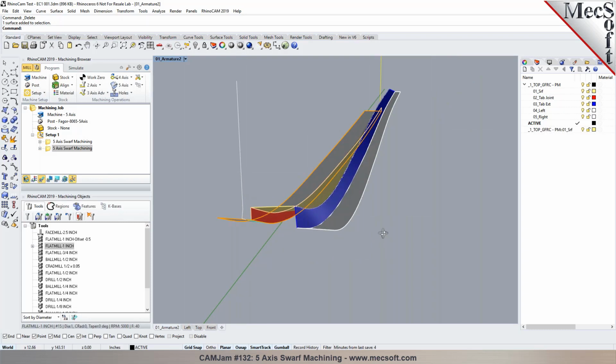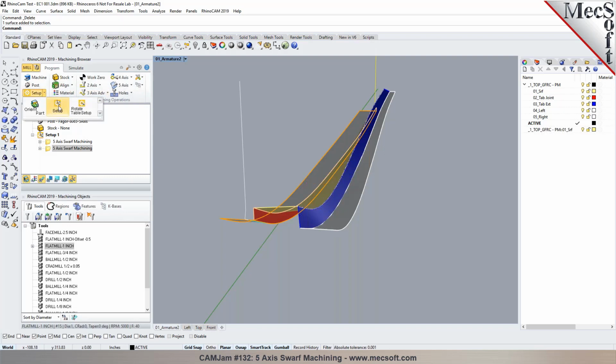While you're demoing that, I have another question that maybe you can answer both at the same time. Sure. So flow line surfaces in the 3-axis, if you're surfacing using the flow line, can you select multiple surfaces in the same operation and have it calculate those simultaneously, or do you have to do a separate operation for each? You can do them as long as it's in the same orientation.